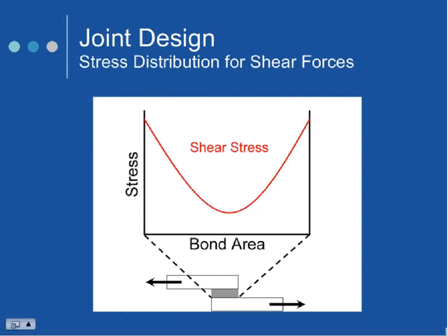And it becomes very critical, especially in medical device manufacturing, because you're working with unreinforced plastics that have a lot of bend and give and flexibility to them. And shear forces, as we'll see in a few minutes, can actually turn into peel forces. And we're all a little worried about peel forces, right?